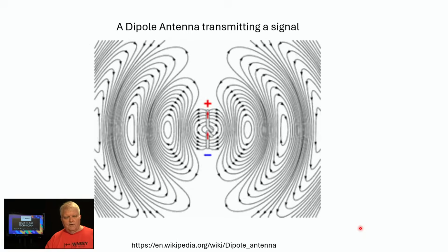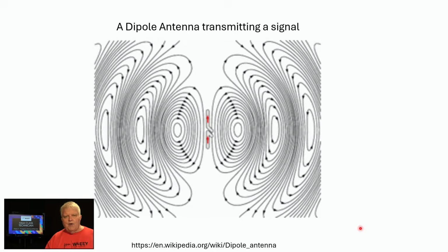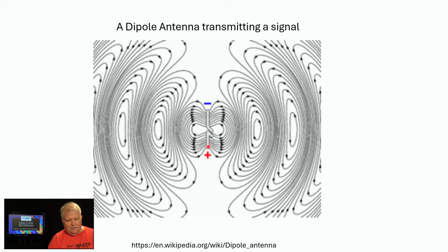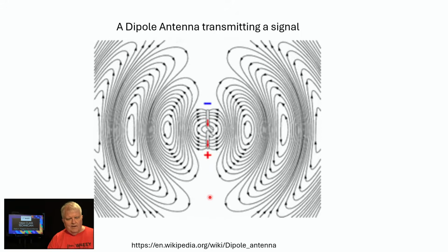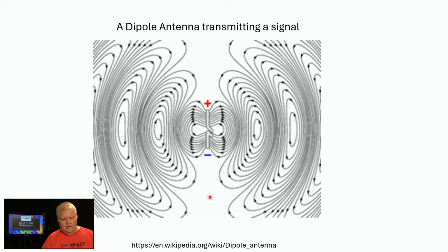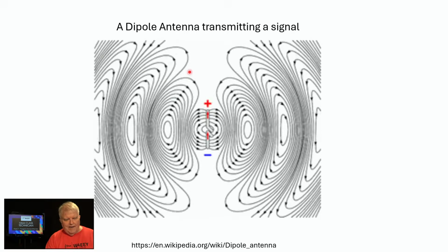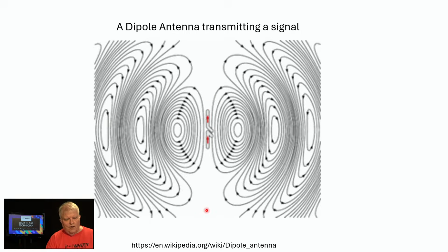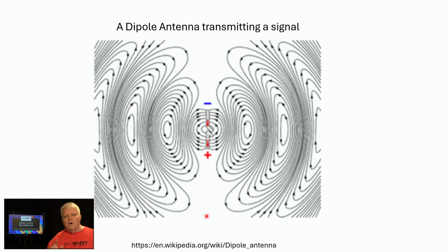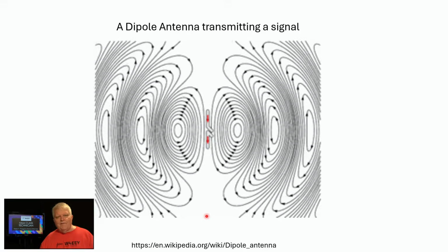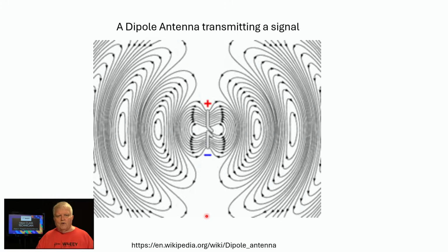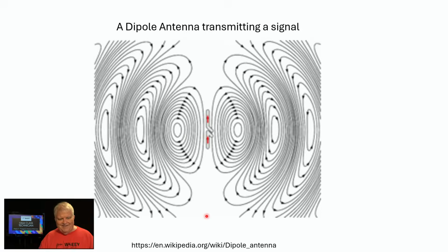And also, here's a dipole antenna. We're looking top down on it now. It's kind of vertical to our orientation here. Here's the dipole antenna. And you can see its radiation pattern off the sides of the antenna. Note there's not much being radiated at the ends of the antenna. That's normal. So your positioning of the dipole antenna is important. If you want to work Europe with that antenna, you have to have it broadside to Europe. If you have the ends pointed toward Europe, you're not going to get them. It's just not going to work.